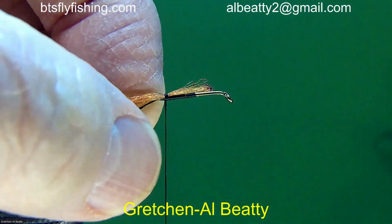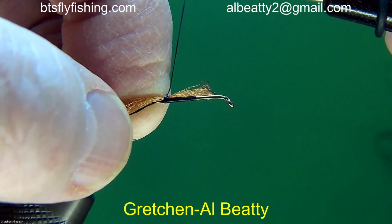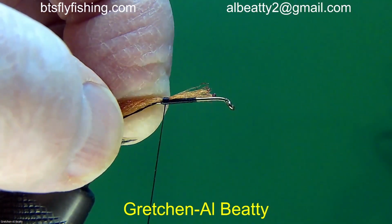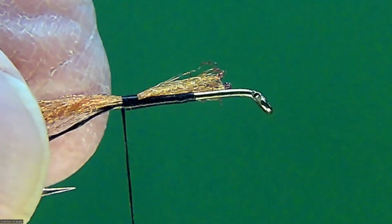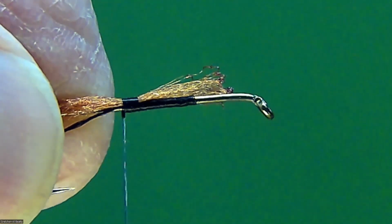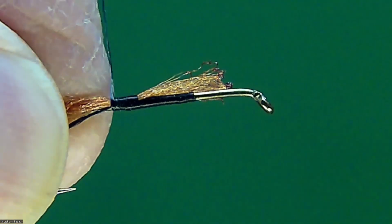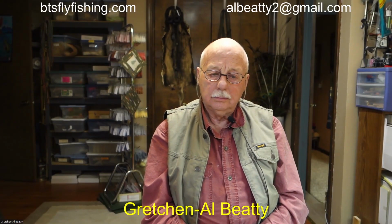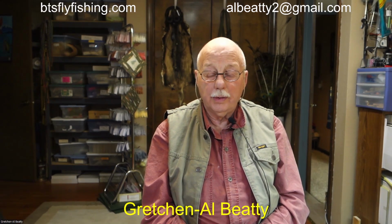That's how you control that material in this particular application. Let me show you what I'm talking about. As I wrap, as the thread comes up and over, I roll my finger forward, forcing the material to stay there. Let's take a close-up look at that. Rolling my finger like this to force that material to stay on top. It's not after the fact, it's at the same time. There we've taken a look at thread torque. It's kind of a hidden force. It tries to position materials where you don't want them.